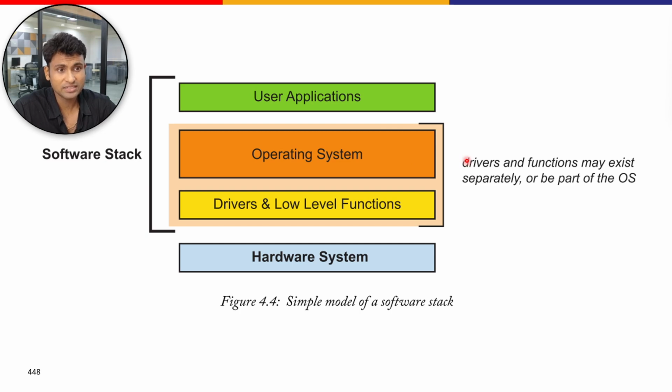Next comes the operating system. This is the orange layer which you can see, which sits on top of the low-level drivers and provides a higher-level abstraction for managing hardware resources. In embedded systems, commonly used operating systems include Linux, FreeRTOS or custom real-time operating systems. We even have a variant of Linux called PetaLinux, and even Ubuntu-based systems running on FPGA.